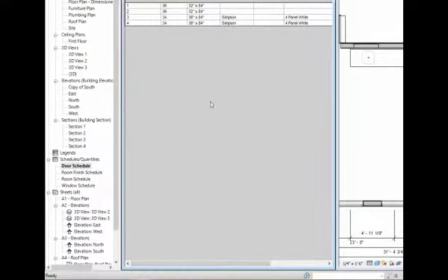Okay, so tagging is just a nice way of relating things together. I have that schedule which shows all the information about the doors. I don't want to repeat all that information. I just really like to refer you to the schedule. So tagging lets me do that. Okay, let's pause there for just a second. So tagging and this whole notion of pulling some value that you want to see about a door or a window into the floor plan view. Let's see how that's setting with people.